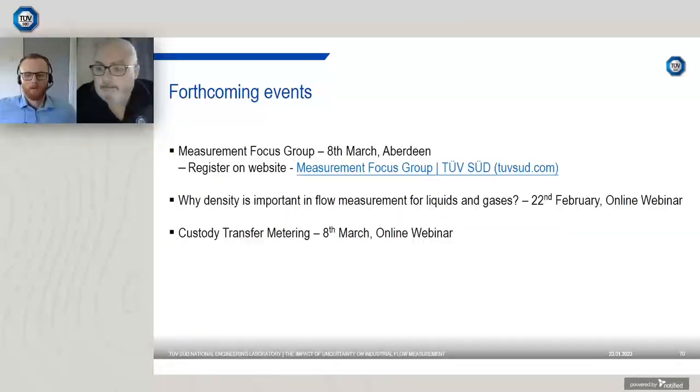Okay, yeah. Essentially, if we look at our practical examples, we have uncertainty budgets for our flow facilities. What this does is look at the reference instrumentation, whether it be a primary standard or a reference meter. And essentially, we go through the process, as I said, looked at in the practical examples. We determine all of the uncertainty sources in our facility and work out what the overall uncertainty in flow rate of our facility is. Without developing these budgets, there isn't any credibility in our testing. If a customer comes to test a flow meter or other device, we need to have live, active uncertainty budgets to state that this is how accurate our facility is, and we can assess your meter against this uncertainty level of our facility.